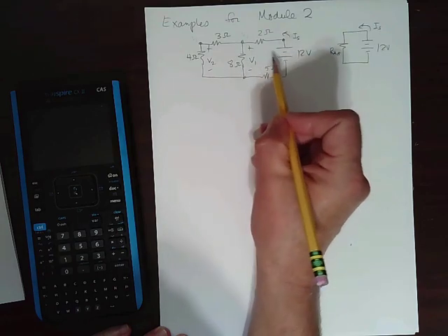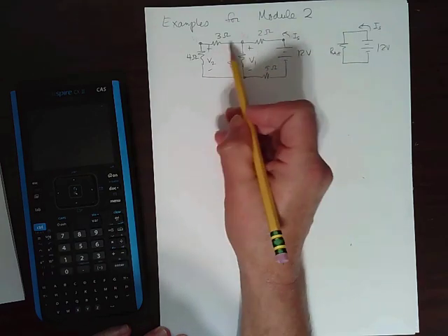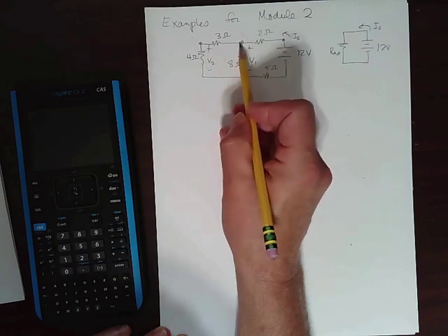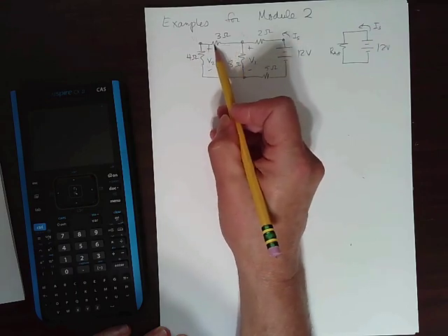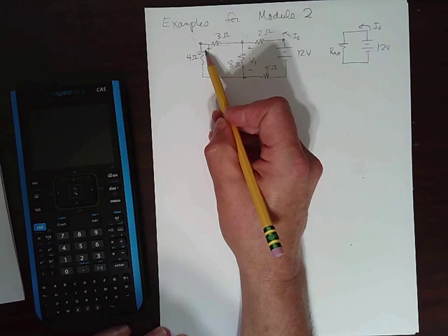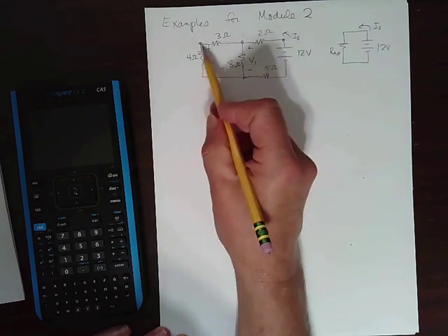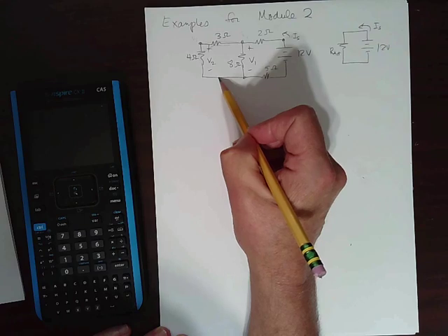And so what do we have here? So looking at this circuit, hopefully you can see these two, the 3 ohm and the 4 ohm, are in series, right? Current's flowing through here, through the 3 ohm. It has nowhere to go, can't escape anywhere, it has to go through the 4 ohm. So they are in series, right? So we can combine them in series.